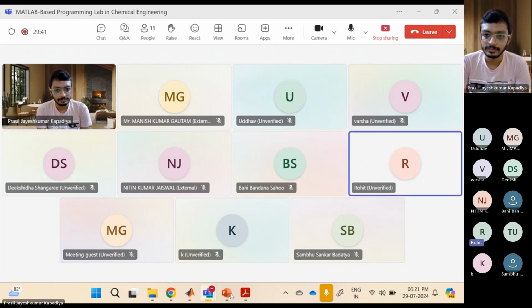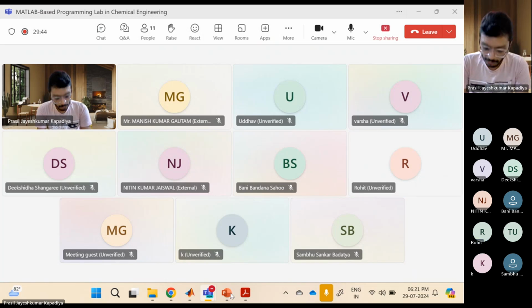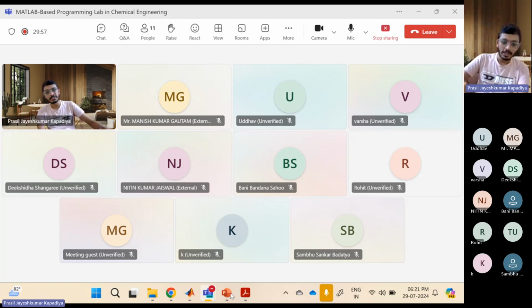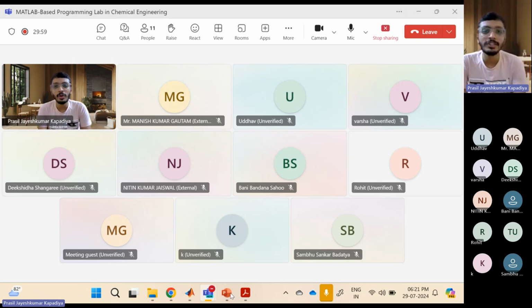Falling materials are always passed through tubes. Okay, so your reason is correct, but here what is happening? What is flue gas? Can anyone tell me? I have written it down: gases emitted from combustion processes. Those are mainly gases like CO2, H2O, N2, NOx, CO. This particular mixture is called flue gas. This flue gas is highly corrosive in nature.